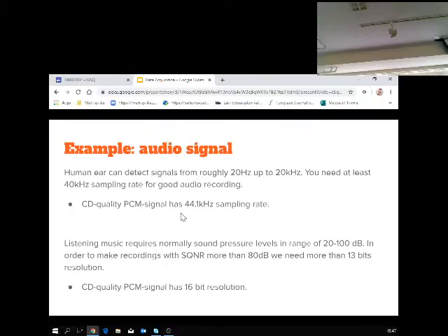Okay, let me just draw it quickly. It means that if you want to sample up to 20 kilohertz and you have analog filters, you need the anti-aliasing filter, and it has an edge. You need to filter those spurious high frequency things out before 22.05 kilohertz, which is the Nyquist frequency for that one. Okay, so there's a reason for everything.